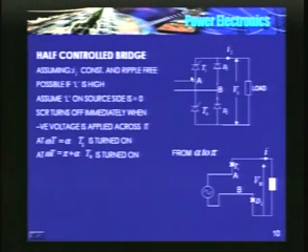Let us assume that in the positive half, at omega t equal to alpha, T1 is triggered. In the lower half, since T4 and D2 form a common anode configuration, the device whose cathode potential is least will start conducting, so D2 starts conducting. So this is the equivalent circuit: source, T1, load, D2, and back to the source.